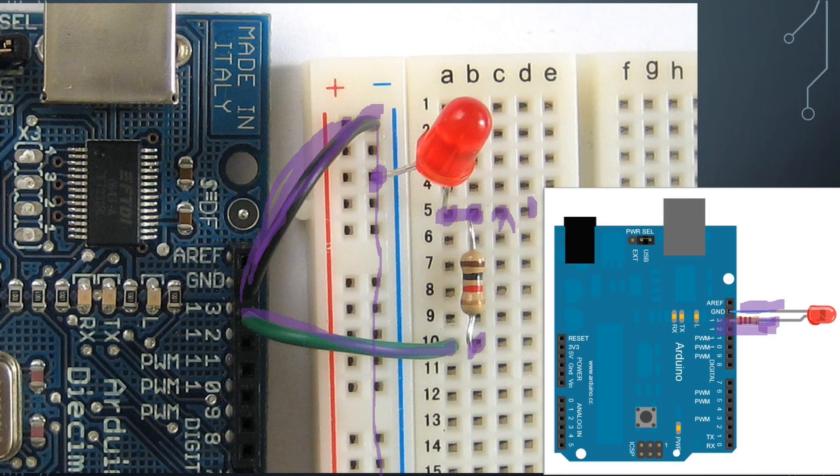And so this is pretty simple. This resistor could be in a different row. We could connect this to the wire in row 9, row 8, doesn't really matter, as long as you're keeping your rows separated appropriately with your components, and you're grounding things and connecting to the right pins. That's really the most important thing when you're setting up your circuit. But this is the basic connection for setting up an LED.